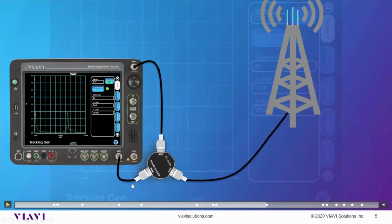So at this point, we've taken that 50 ohm load off and we've connected it to our antenna out here. And we are going to see the spike come up, and that's going to be the end of the cable, or if we're in a troubleshooting mode, we're going to find the anomaly along the way that's possibly causing the issue.